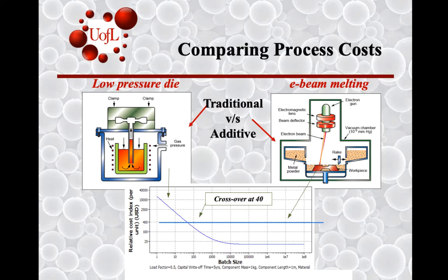But largely, when you have a die, you have decreasing costs over larger production ranges, finally limiting to material and labor costs at the high end of batch size. Whereas for processes such as metal additive manufacturing in particular, in this example, you have a more batch size invariant trend in terms of part costs.